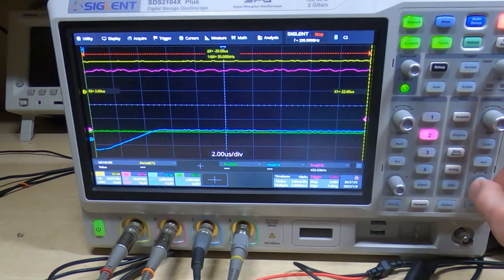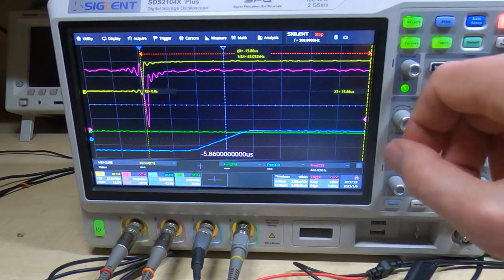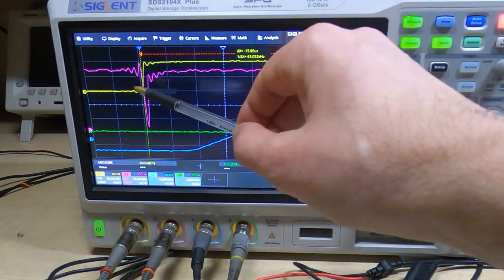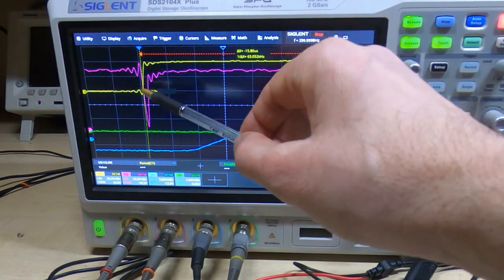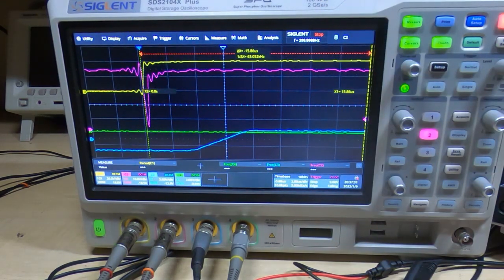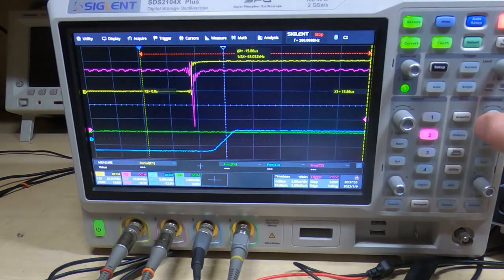It's quite hard to see because we're not capturing that much data on this, but in this case the rising edge of the yellow trace is before the rising edge of the purple trace. In other words, the first clock pulse being fed to the counter occurs during the reset pulse, and that causes the reset value in the internal counter to be latched into the output register, and then it's prepared now for the proper sequence.